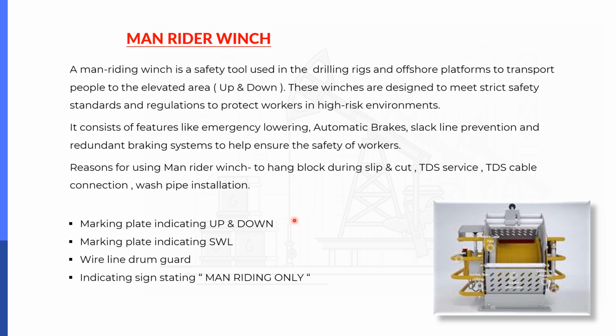Whenever the man rider winch is used, a work permit is required. The rotation of the drill string and the hoisting of the traveling block will be stopped, will be paused, and there should be a proficient operator who will control the man rider winch. There are many other points related to the man rider winch, which I will mention in a separate video when I make one for the man rider winch.